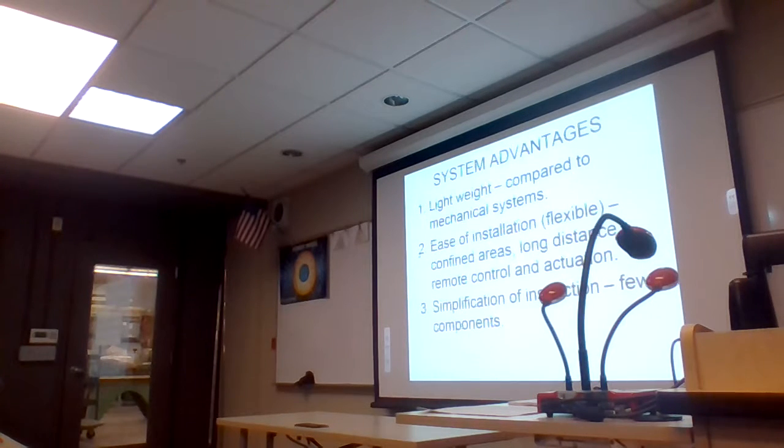When you want to transmit force with mechanical components, you have to have a series of pulleys and bell cranks and push-pull rods in order to direct that source of force to a different location, pretty much along straight lines that have to make turns and bends. And the only way you can do that is with mechanical components to connect the things. With hydraulics, we can route a hydraulic line from one location to another through confined spaces and bring it to an actuator that's very remote from where we're at without too much difficulty. So from a manufacturing standpoint, it makes things a lot easier to do.